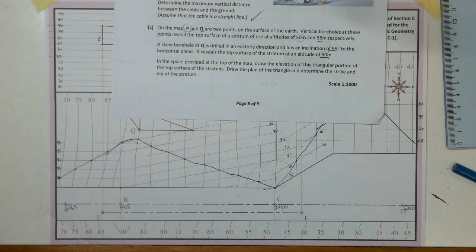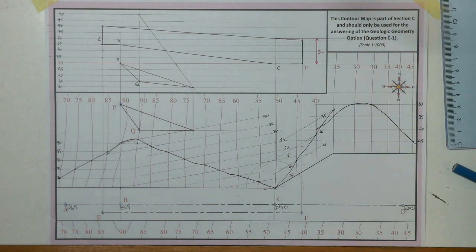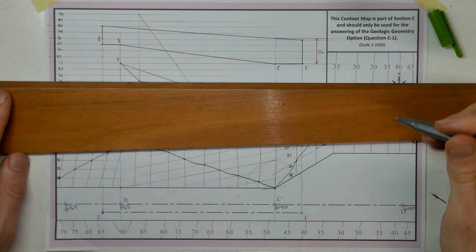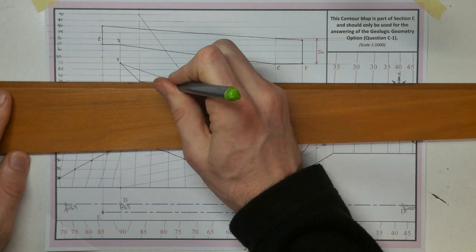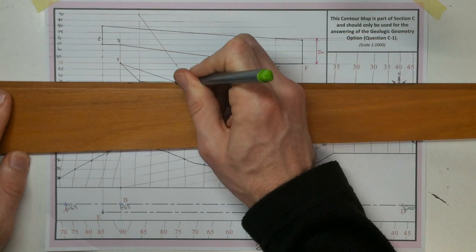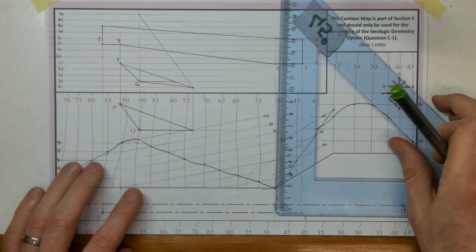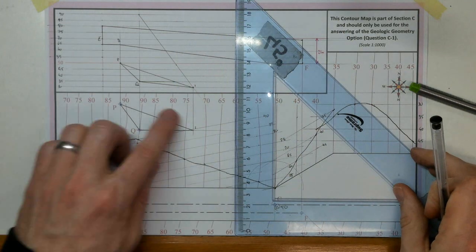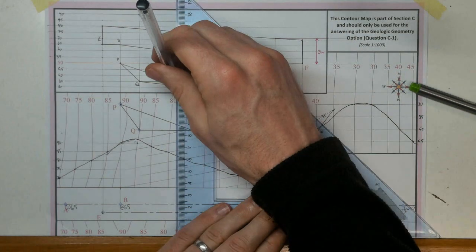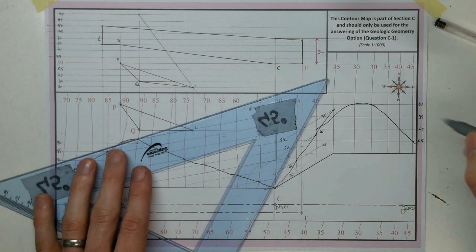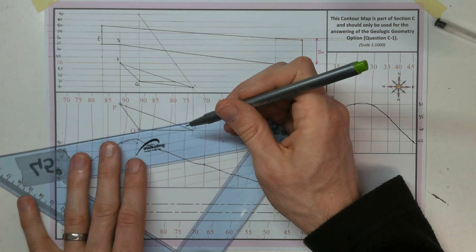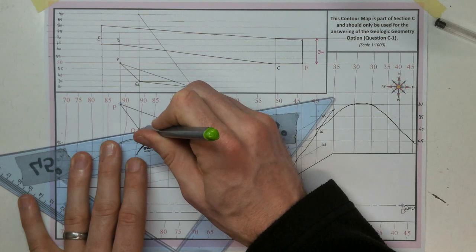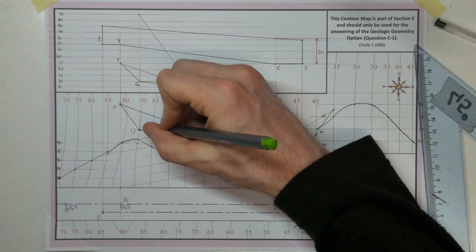Strike is a level line on the surface, so let's locate that level line and use a marker here. That's where it intersects that plane. We'll call this point 1. On P1 we'll drop our level line onto that, so that locates our strike. Okay, so our strike.